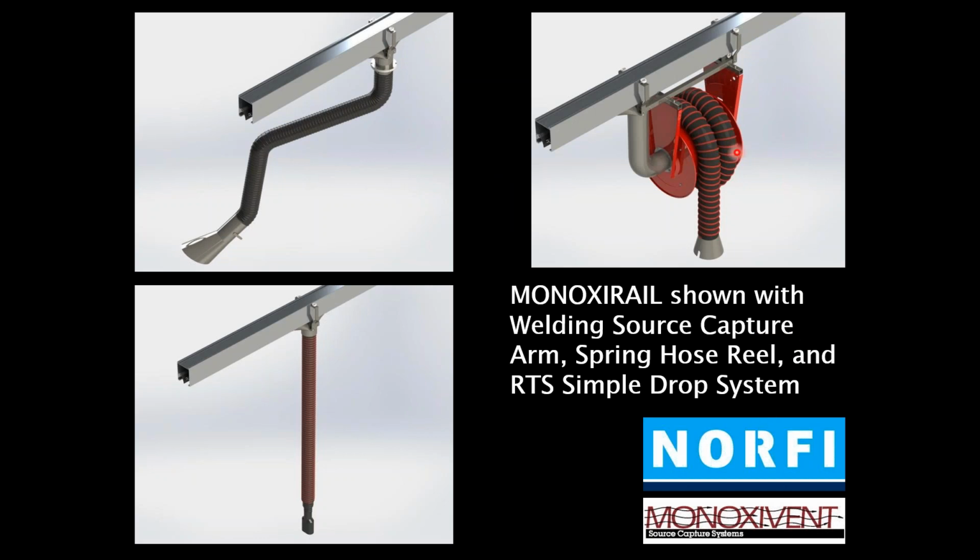Now, I told you earlier we can do overhead systems, we can do hose reels, and we can do the RTS system, but we could also do this for welding applications. So maybe you have 5 welding stations in a row, but you only have 2 welders. Well, in that case, you'll never weld more than, you know, two of those stations at a time. So I could run my rail from bay 1 to bay 5, put my 2 drops in, and this can travel up and down wherever I need it to capture that welding exhaust.